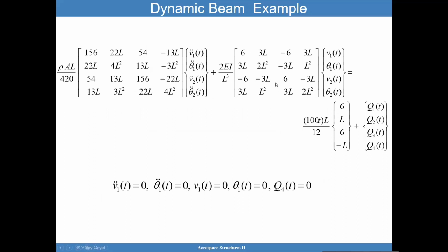So here's a stiffness matrix, and then here is the vector of unknowns, deflections that are unknown, and here is the distributed load that we talked about, and also then you have these loading conditions. These are concentrated loads that you could apply.